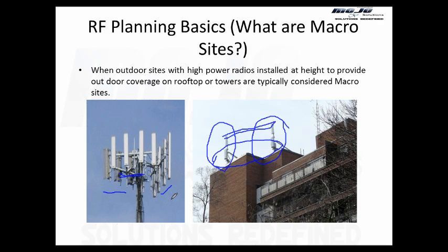Because the site construction team needs to know what to deploy and how to deploy irrespective of the technology. They know what is LTE, they know what is UMTS, which cabinet belongs to LTE, which cabinet belongs to UMTS, which antenna is connecting to LTE, or maybe LTE and UMTS both are going to the same antenna. Maybe the antenna is a quad pole antenna. There are hundreds of considerations.